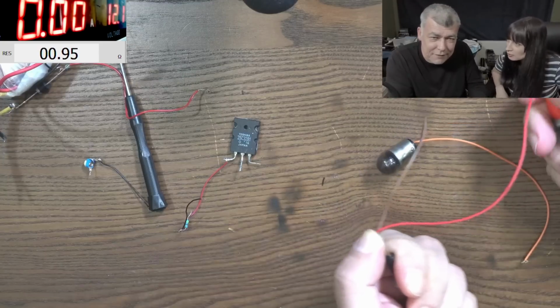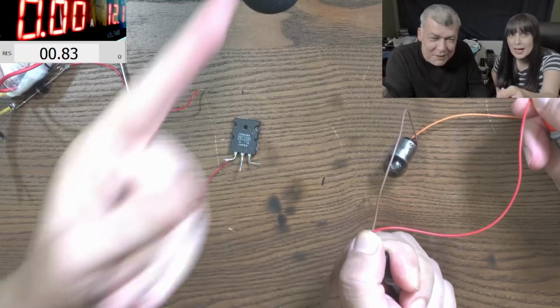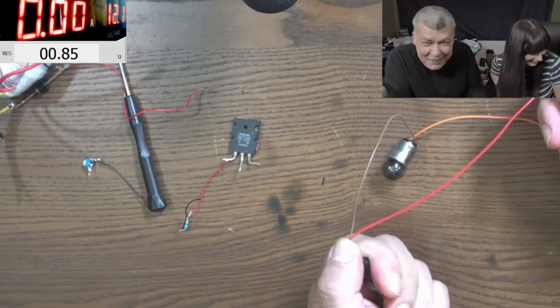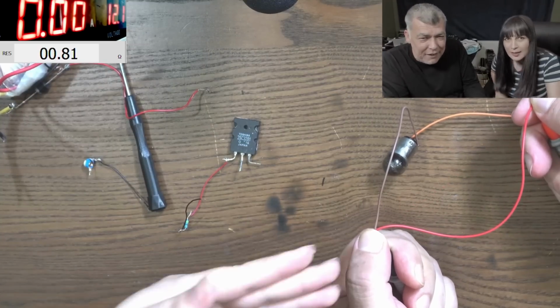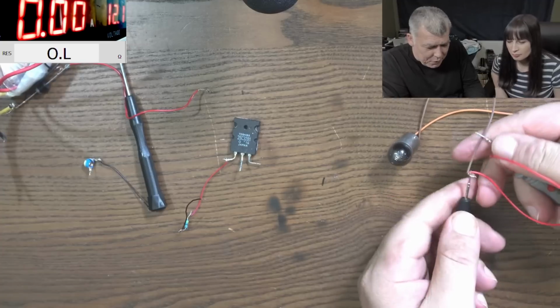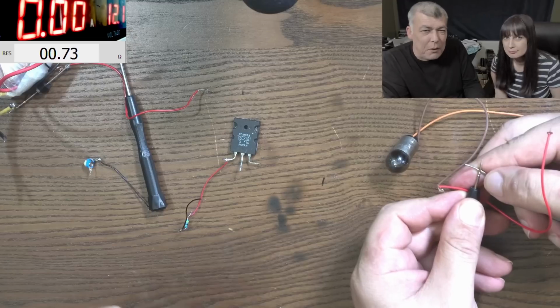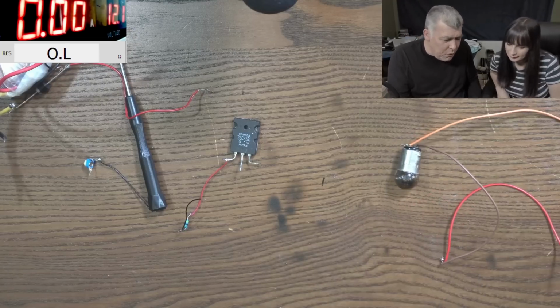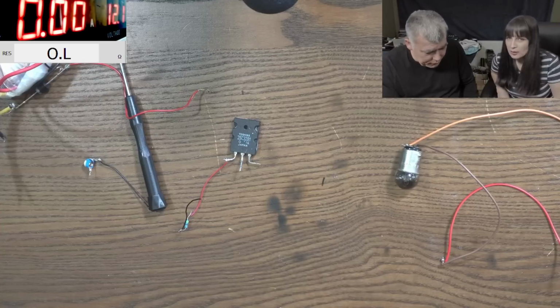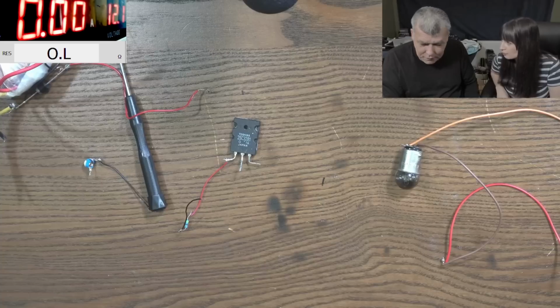You're not touching. You are not touching. Check there. It's there, 0.8, right? Yeah, but earlier was 0.9. If I touch those two, it's about the same. Yes. Yeah? All right. So what is the resistance of the wire? It's 0.1. 10, sorry. It's 0.10. Okay.